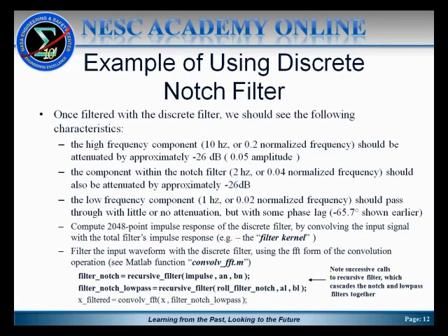Because again, as we've mentioned before, convolution is very, very slow if you just do it the brute force method, the summation, where you sum the terms together, because you're doing order of n squared calculations. And so with a 2048 point sequence that we're going to be convolving here, that would be like 2048 squared, or a lot of calculations. So the FFT form of the convolution is very much faster than what you would get if you just did the so-called brute force method. So another thing, a couple things to notice here is we've got a 2-stage filter.